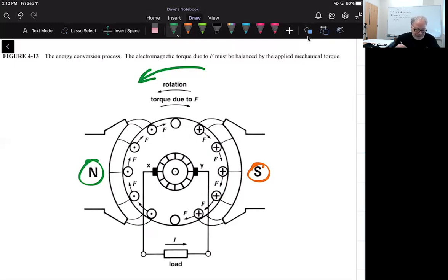So all the currents have that particular direction because of their being under the North or the South Pole. Because these conductors, which are current carrying conductors, are exposed to a magnetic field, they are subjected to a force. This has been mentioned before, and I will do a side video and explanation about this phenomenon called Lorentz forces.